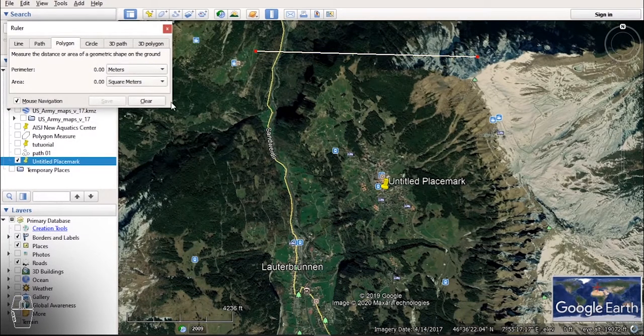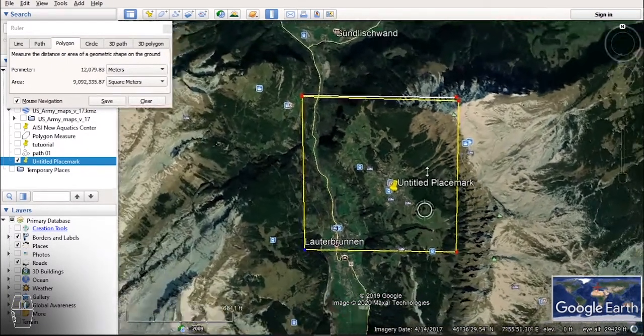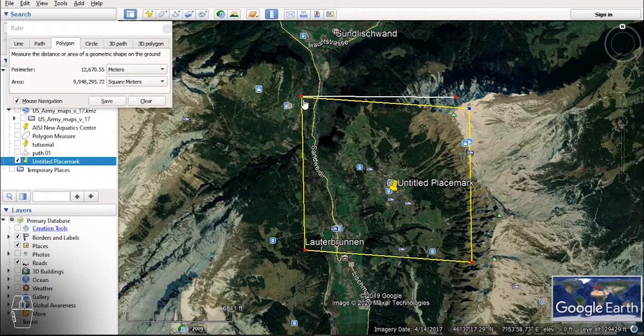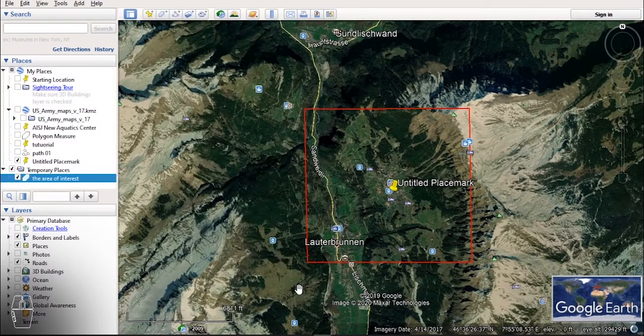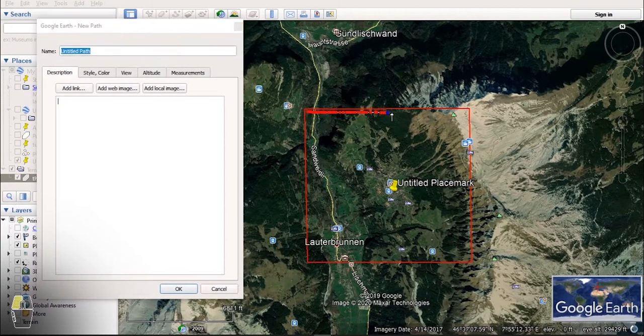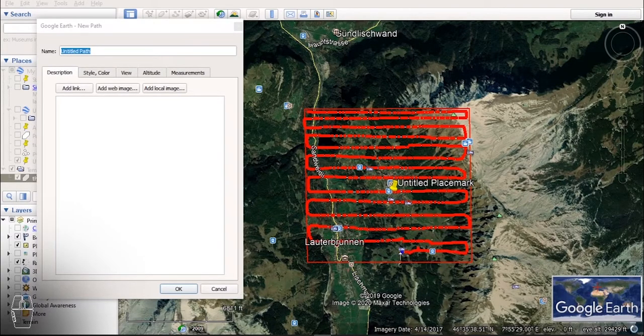The first method, which is the free one, is based on extracting the elevation points directly from Google Earth Pro by drawing a path on the desired area. The points should be as dense as possible, because depending on your location you may be looking at a 10 meters resolution terrain like in the US or a 30 meters one like in Northern Europe, and just to be on the safe side, make sure that the distance between each point and the other is at least 10 meters,